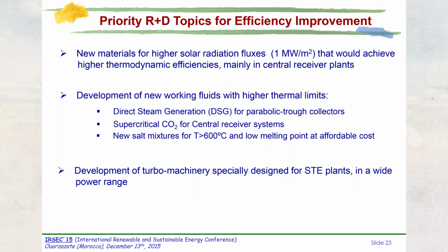So the technology is ready, but the main problem for the commercial deployment of this technology is the lack of a suitable thermal storage system, because we need a phase change material. So we need thermal storage based on PCMs, the technology already explained by Professor Bassin in the previous talk. And such a technology is not yet fully commercially available. There are some prototypes and there is a lot of research concerning development of phase change materials,